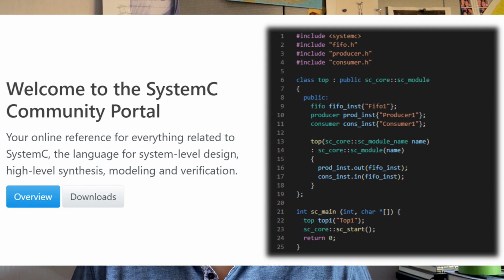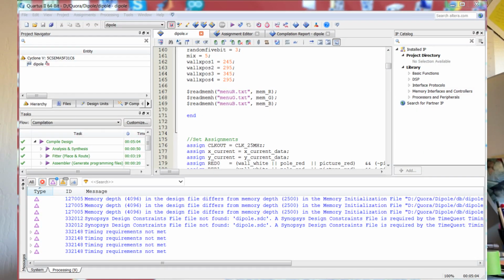Those languages are very high level, and they're useful because you can design things quickly. But the problem is ultimately the chip is not as efficiently implemented. And so the vast majority of chips are made with Verilog or System Verilog. So if you want to go to school and learn how to make chips, make sure you learn Verilog and System Verilog.